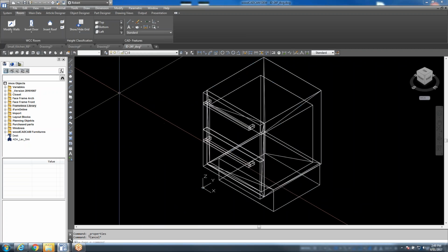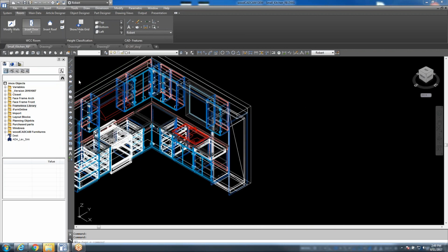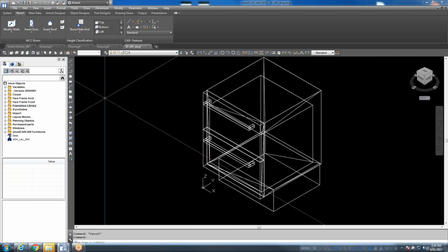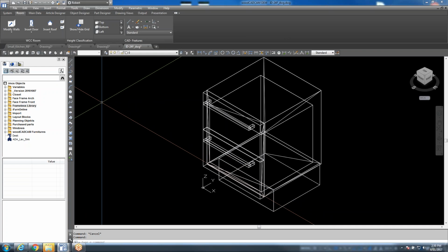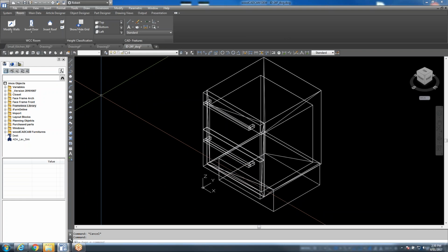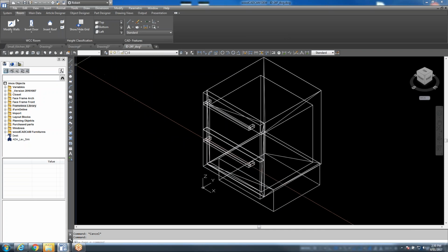All right, on your WoodCAD CAM Manager, we're on the first tab there. Should I stay on that drawing? Yeah, go back to that drawing. With the drawing open of your block, you'll see on the first tab on the right a little fancy F with an arrow next to it. On the main insert tab, the WoodCAD CAM Manager is the dockable container on the left side of your AutoCAD window. No, move your mouse down. See where your library is? That's your WoodCAD CAM Manager.